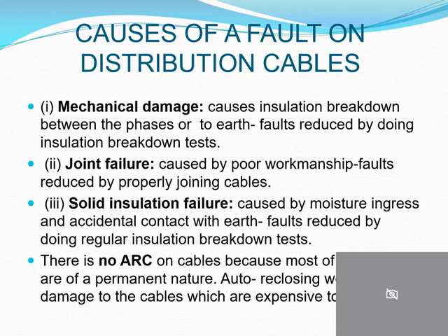And then for your water ingress or your moisture that you have in there, it would assist if we make sure we put our cables in ducts. And in most cases, we run away from that because it becomes expensive putting all of those pipes underground in order for you to pull the cables in.